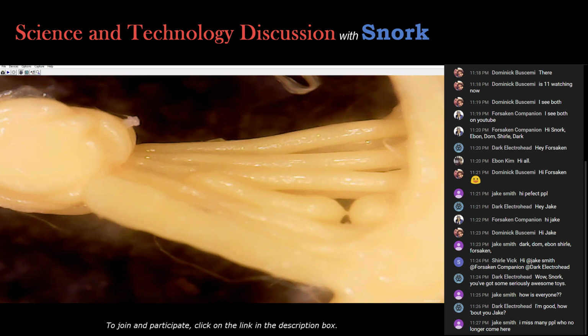As you can tell, when you get really in there, you just see blobs here and there. That's because this was a trial where I wanted to set the machine up to extremely high performance, which means you've got to make a bunch of tests and see how I have to tune the machine to get there. So this is an early reject, but early rejects are really good for showing problems. Other things that can be done, you can change the type of plastic. This will have ripples on it.